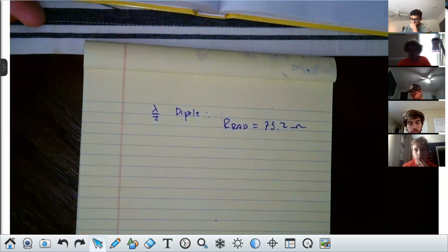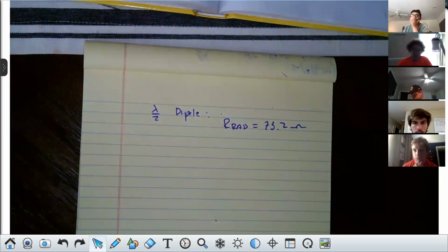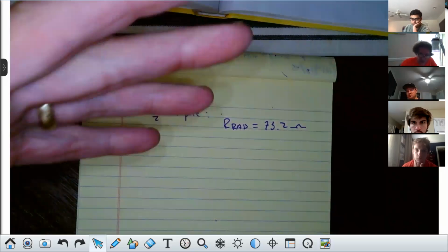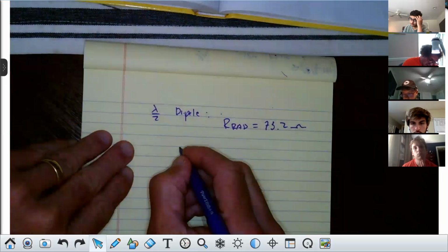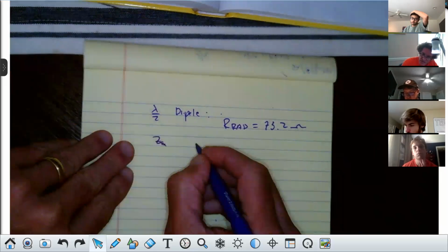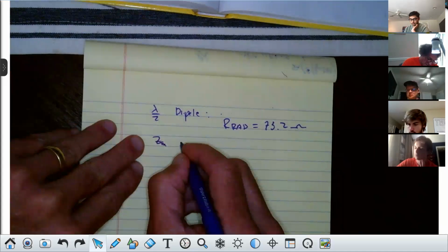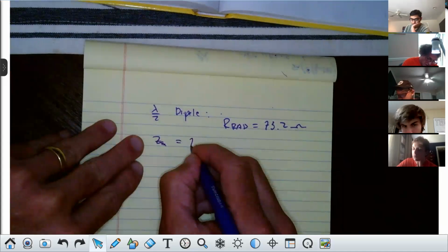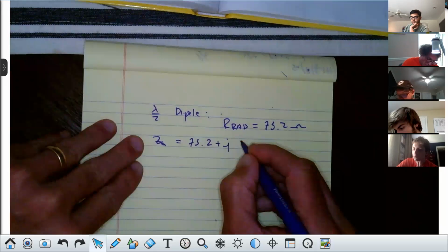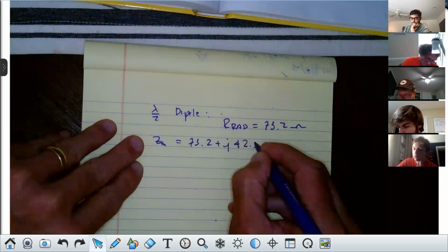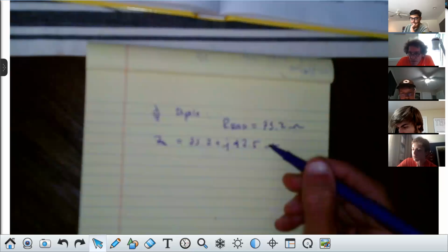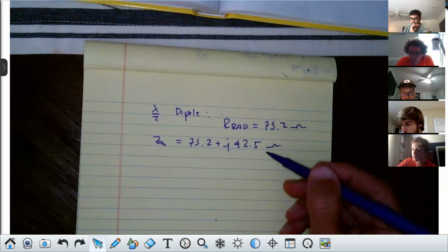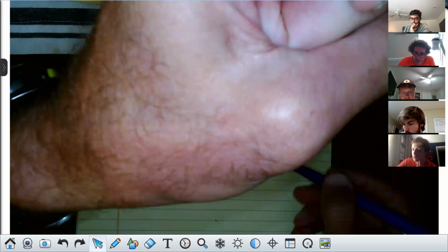Now remember, I told you that antennas have a reactive component that has to do with the electric and magnetic energies nearby, right? So normally the actual input impedance on an exact half-wave dipole is equal to 73.2 ohms, but then it has a reactive component of about 42.5 ohms. That will vary somewhat depending on the diameter of the wire used for the antenna.